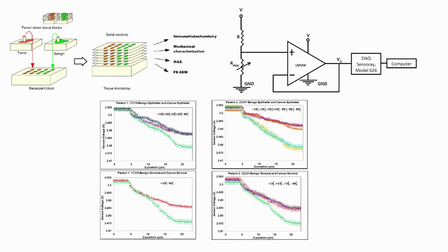The idea is that if I now have a piezoresistive microcantilever, and if I press it against a tissue, how can I see the change in the resistance or change in the voltage, right. So, you can see here initially it is close to 2.5 volts when both the resistors are balanced. That means, whatever the resistance of the piezoresistive microcantilever is, the same resistor value I will use here, and then initially, because of the potential divider, I will have a voltage of 2.5 volts.